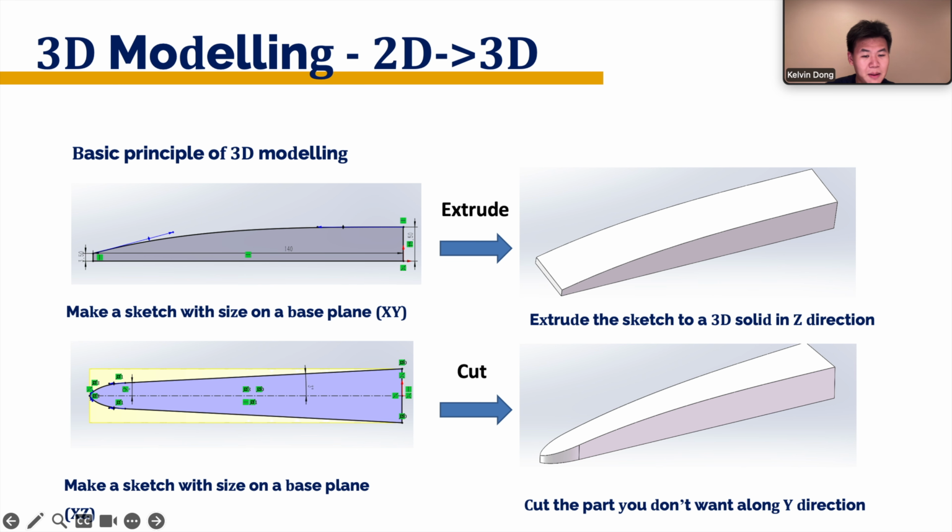Do not overcomplicate early geometry. Focus on controlled dimensions and references, not cool shapes. If your base sketch is clean, editing later is easy. If your base sketch is chaos, every single edit in the future will be painful.